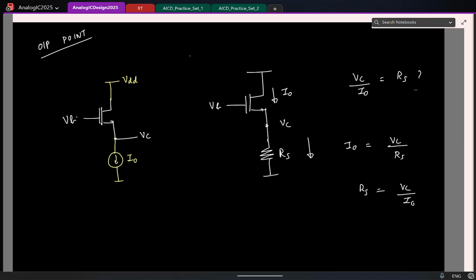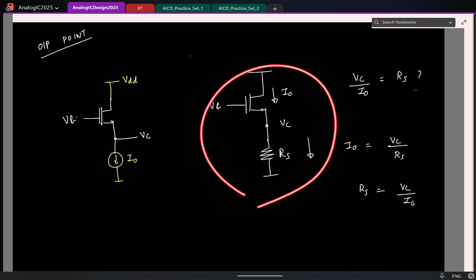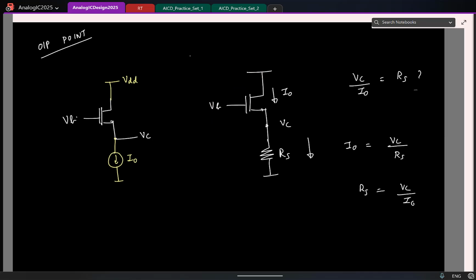remember, this is basically the inverse of the substitution theorem. The substitution theorem says if I have a resistor, as long as I keep the same voltage and current across it, I can replace the resistor by an equivalent current source. The value of the current source should be the current flowing through the resistor. Then the circuit will have no idea what happened. For all that it knows, the same current is getting pulled out. KCL has to be satisfied, so the voltage will remain the same.